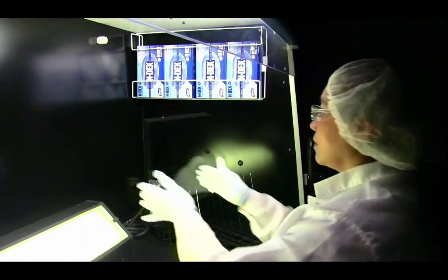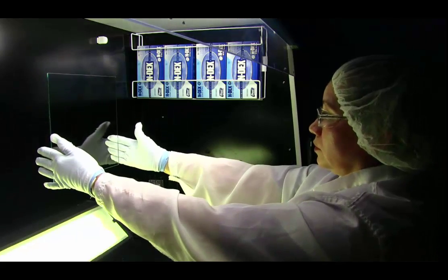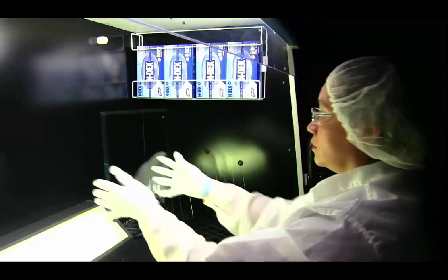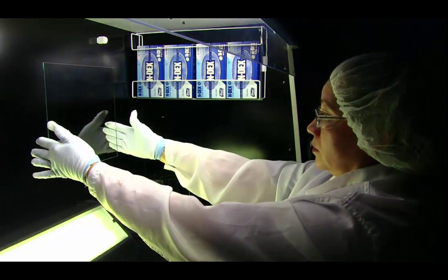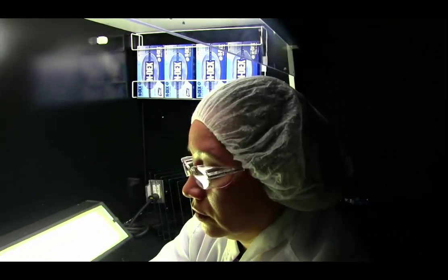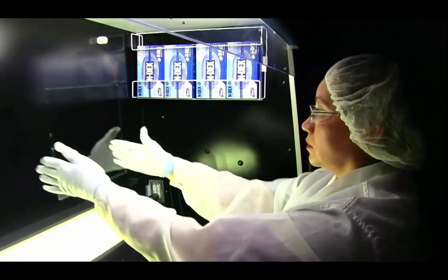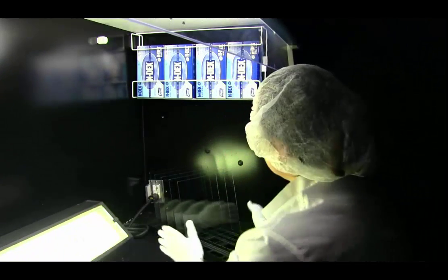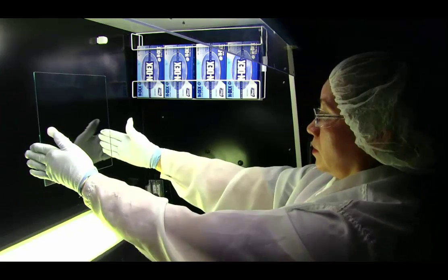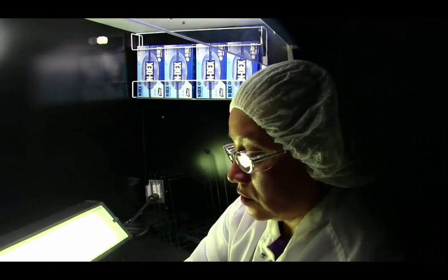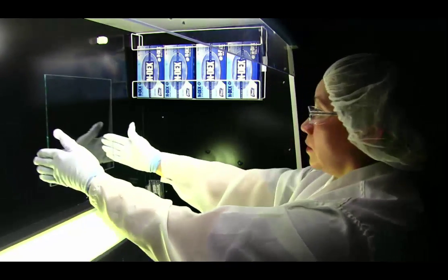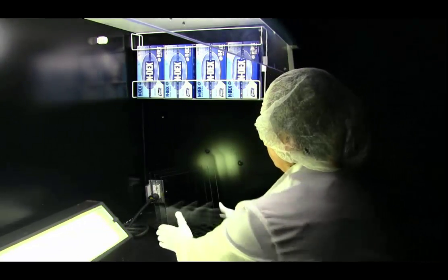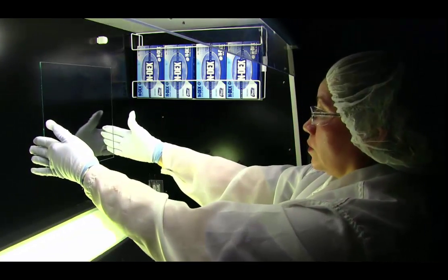Parts are handled by the edges of the glass as demonstrated by the inspector. The inspector is required to wear barrier gloves to protect the edges of the glass from contamination coming from the hands. Parts are viewed in transmission perpendicular to the eye, approximately arm's length distance or 18 to 24 inches as our specification calls for. Similar to 6040, the part is scanned top to bottom, left to right, for a period of 2 to 5 seconds, looking for common defects such as digs, scratches, chips, or other blemishes present on our glass. Parts that meet criteria are then set aside and processed further throughout our facility.